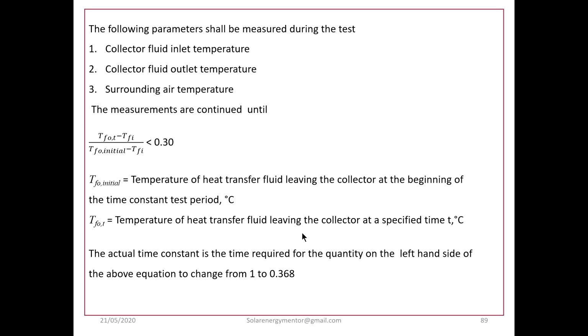Collector fluid inlet temperature TFI, which is maintained, collector fluid outlet temperature, and then surrounding air temperature. Now the measurements are continued until (TFO,t minus TFI) divided by (TFO initial minus TFI), this ratio, becomes less than 0.3. In the above expression, what is TFO initial? TFO initial is the temperature of heat transfer fluid leaving the collector at the beginning of the time constant test period, and TFO,t is the temperature of heat transfer fluid leaving the collector at a specified time t.